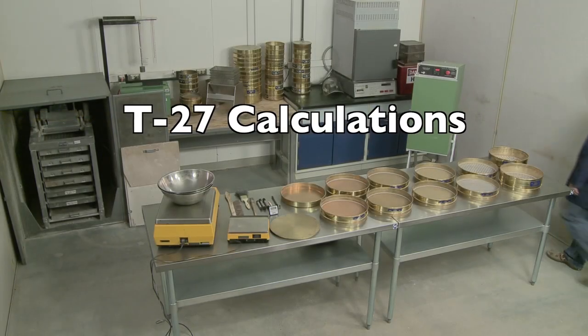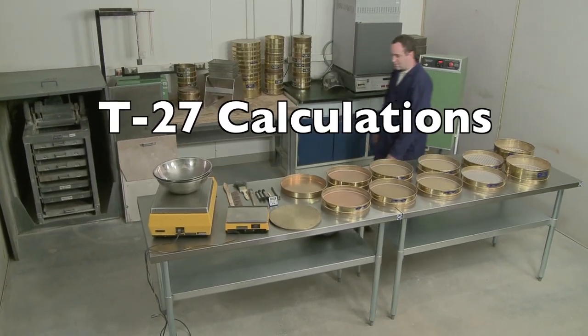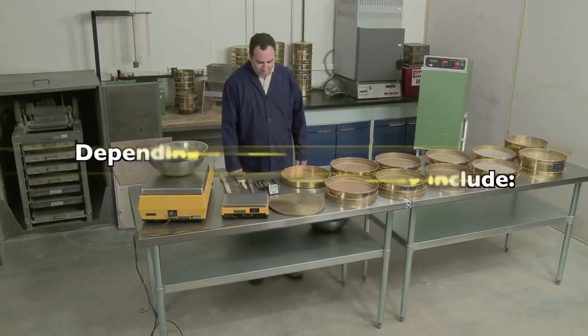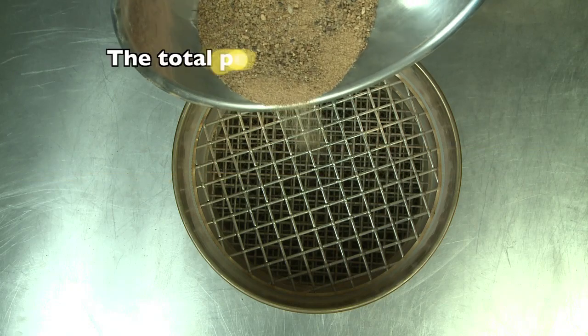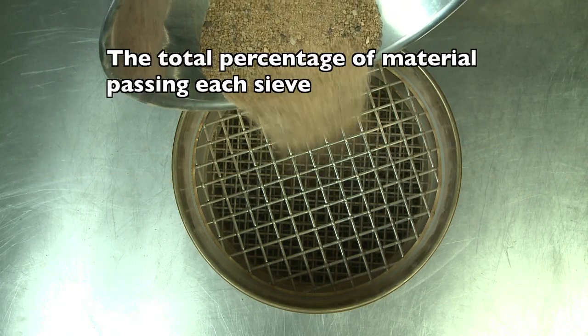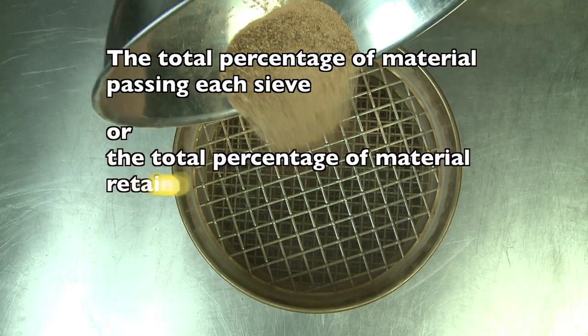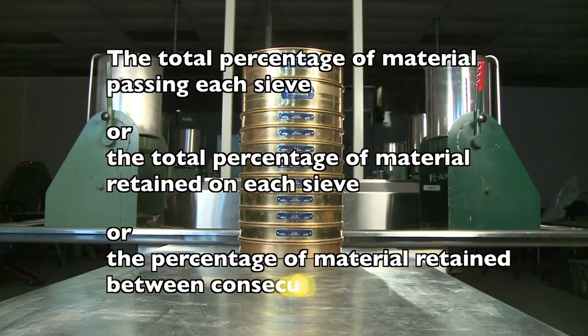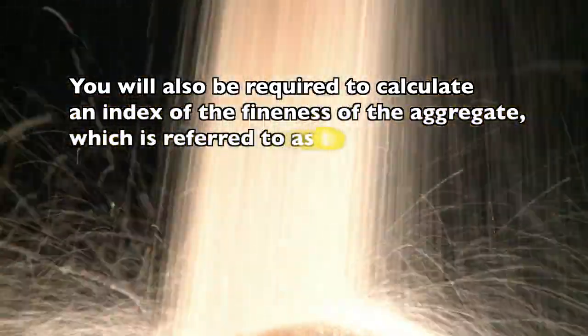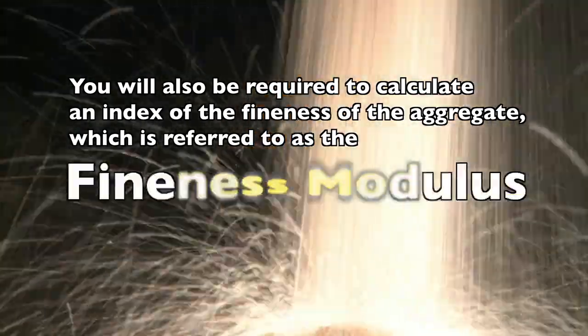In this section, we will cover the calculations required for T-27. Depending on the specification, sieve analysis calculations may include the total percentage of material passing each sieve, or the total percentage of material retained on each sieve, or the percentage of material retained between consecutive sieves. In some cases, such as a gradation for concrete sand, you will also be required to calculate an index of the fineness of the aggregate, which is referred to as the fineness modulus.